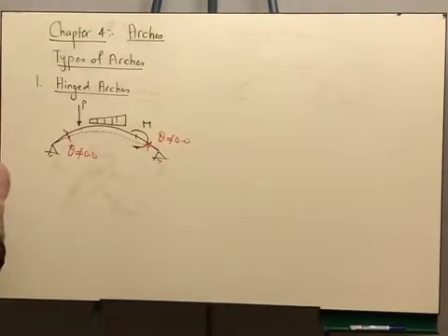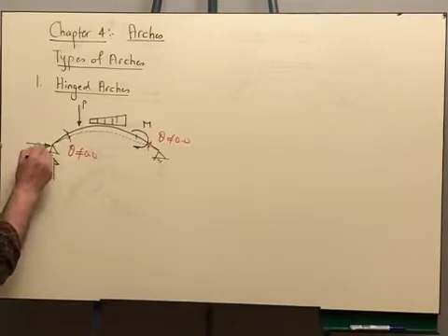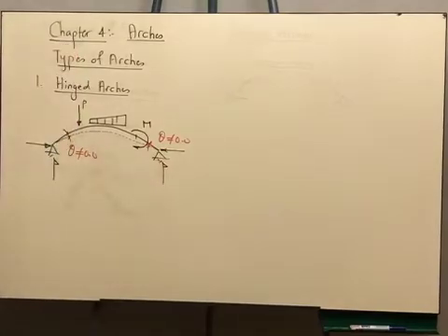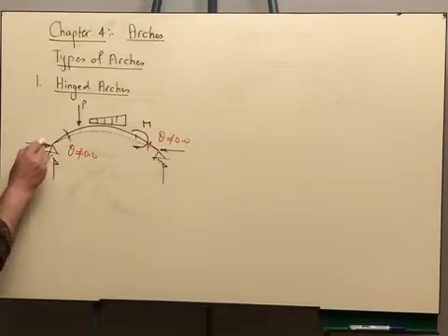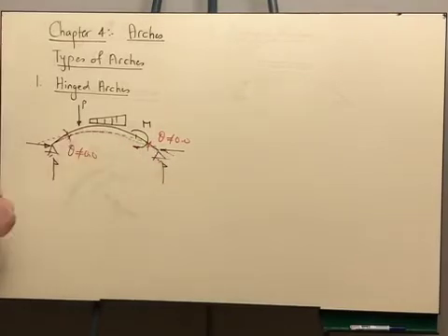The reactions that we have will be vertical reaction and horizontal reaction. Unlike the cables, the horizontal reaction is pointing inward. Why? Because if you removed this support, the arch would like to move in the horizontal direction like this due to the effect of the applied loads. Now this support is prohibiting this movement, so it is as if we are having a horizontal reaction that keeps this joint in position.